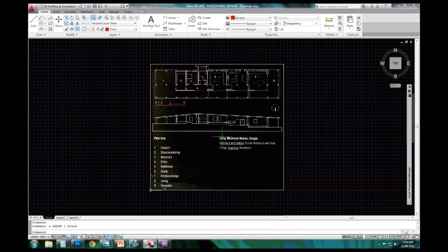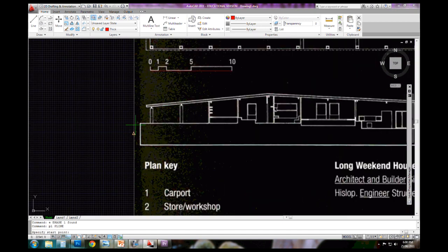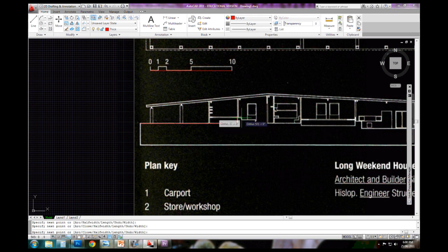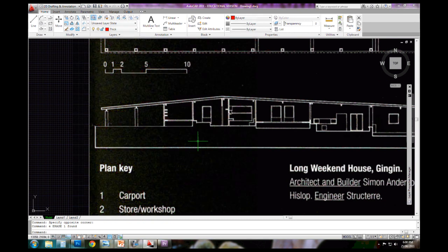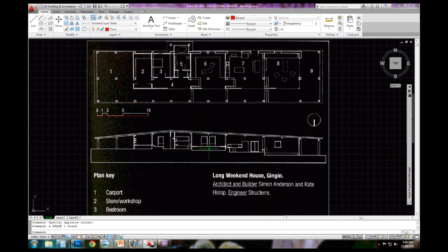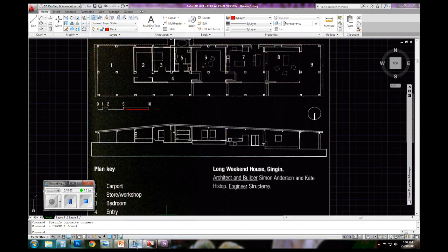Alright? So the thing that I'm going to do, I'm kind of assuming that you're working from a printout in this case. And if you had to actually draw, not by tracing, but by having information that you've got, say you've started to do a sketch of a design, and you want to manually translate that line data into AutoCAD, that's the way that I'm going to draw. I could easily go in here and start to trace over this, but I'm not really learning anything. So I'm going to show you some offset commands, some divide commands to actually establish and finish a drawing. So we're going to use construction lines as well.